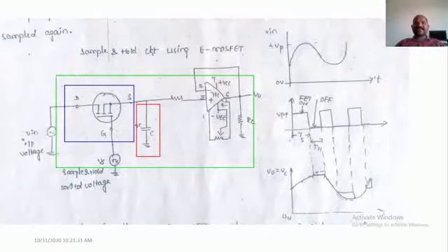So this entire thing acts as a sample and hold circuit, and the held information should get amplified to drive the next level of the device. That's why we are having the operational amplifier, which is nothing but the voltage follower. The output follows the input only, but the output is a high intensity signal.